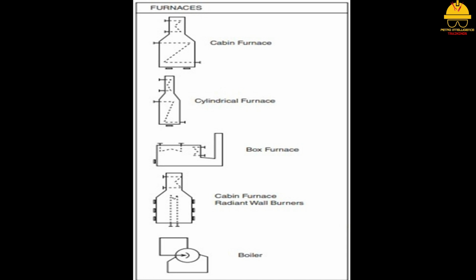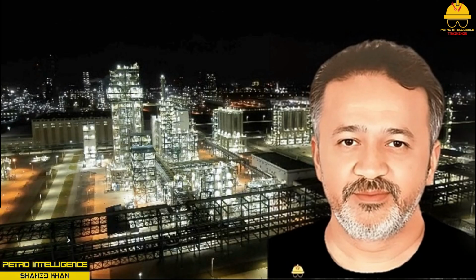A boiler is similar to a furnace, however, it is designed to boil water for steam generation. This process changes the internal arrangement of the boiler. Water can absorb a tremendous amount of heat. When it changes state, it expands to many times its original volume. A typical water tube boiler has a large upper, steam-generating drum, a lower mud drum, and a series of tubes designed to provide natural circulation of the steam back to the generating drum. This picture shows the symbols used for steam generators and furnaces.